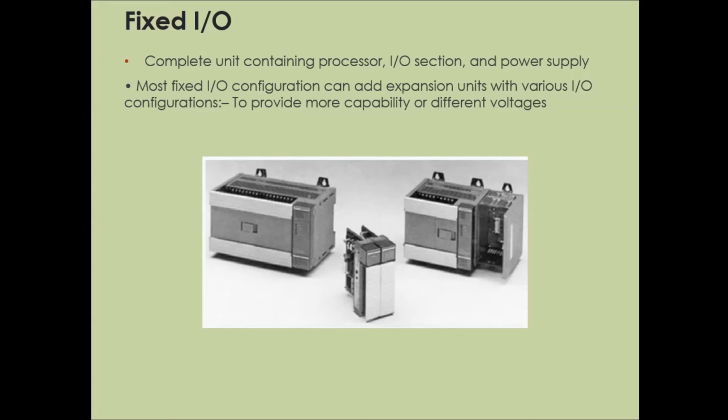Fixed I/O. It is a complete unit containing the processor, I/O selection, and the power supply. So it's one unit. You can see in these pictures below, it's one unit. Most fixed I/O configurations can add expansion units with various I/O configurations to provide more capability of different voltages.